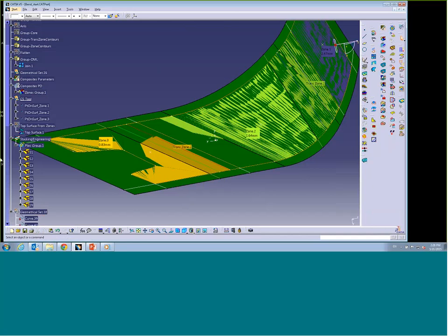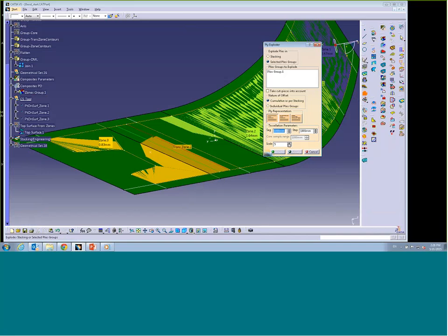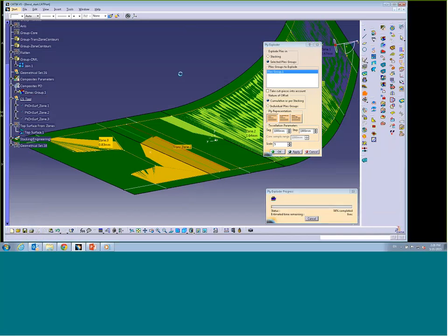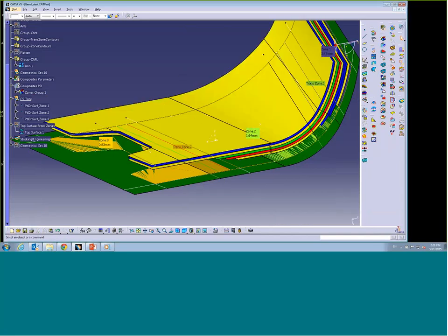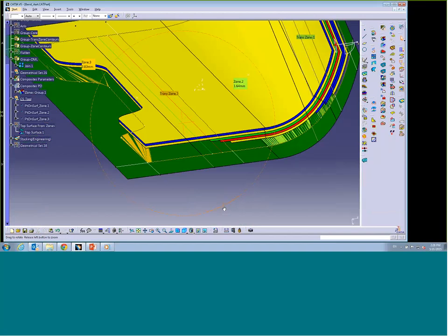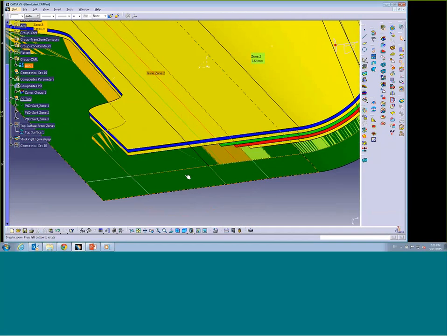And off you go. Okay, so it also created plies group and a whole bunch of plies, but now when I check the sequencing, which is using the ply exploder, okay, I can now see that the plies have been reordered indeed. Like in this specific case, I wanted to avoid to have two plies with the same orientation at the top, and I've just done that.